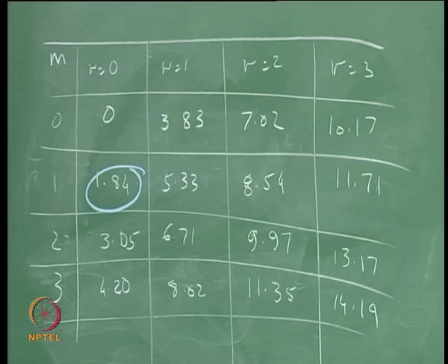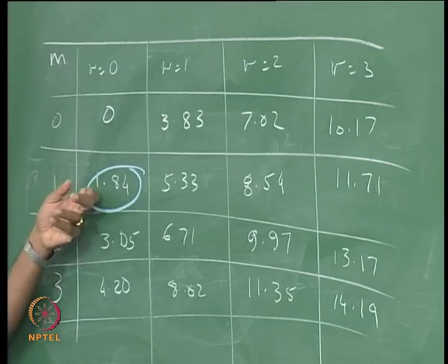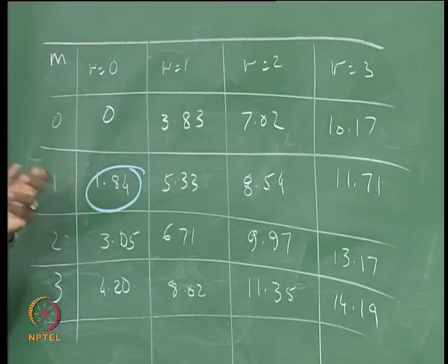Why the roots are this way, a lot of material is available, but we can get this from a handbook. The interesting thing is that this corresponds to the lowest frequency that can be set up with the radial mode, and you can have frequencies only higher than that; anything lower than that would not propagate.